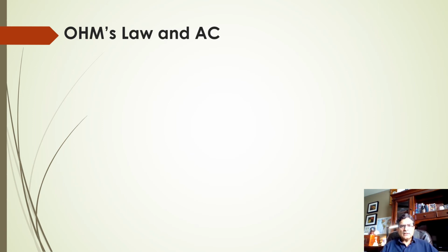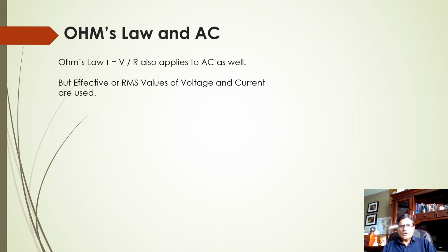AC has. Now how do we compare then, or use Ohm's law on AC? So let's talk about that. Ohm's law actually applies to AC, but with a condition. Ohm's law is I, current, equals voltage upon resistance. It applies here, but with effective values only, or the RMS value of voltage and the RMS value of current.